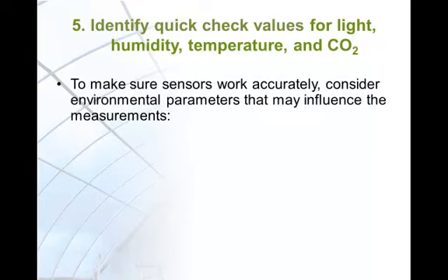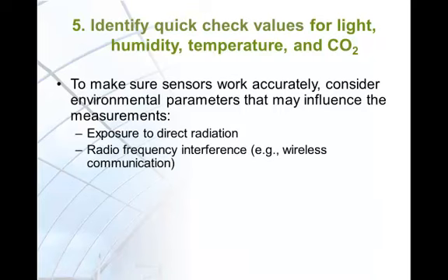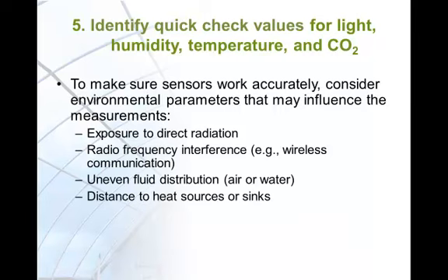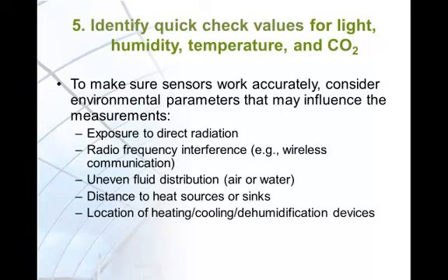To make sure that sensors work accurately, consider environmental parameters that may influence the measurements, such as exposure to direct radiation, radio frequency interference, uneven or unmixed air or water, distance to heat sources or sinks, location of heating, cooling, or dehumidification devices, and random signal noise.